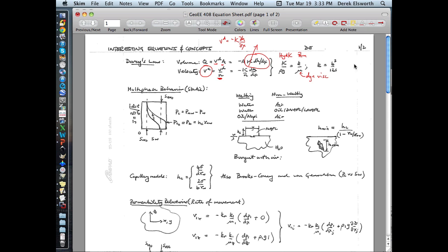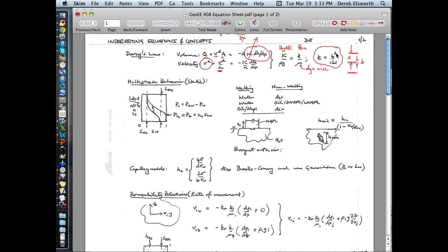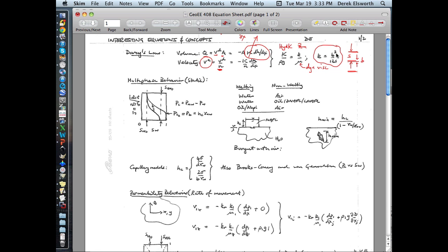We've certainly talked about the permeability of fractured systems, fractured rocks, and you've used that to back calculate entry pressures, where the spacing between fractures is some amount, and the apertures of individual fractures are some amount here. So you've certainly seen that, and you've used that in your assignments. So those are some background expressions that you've used. We talked about immiscible flow. So the behavior when a free product takes days to weeks to months to get to some initial location.